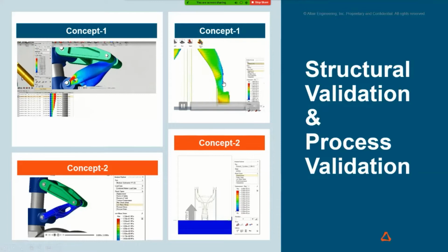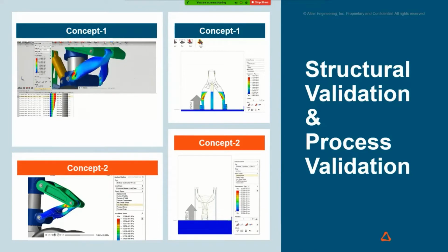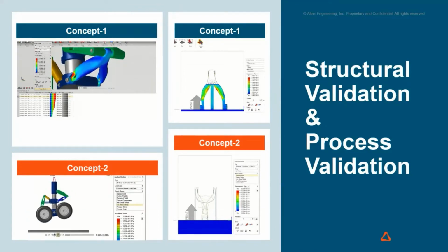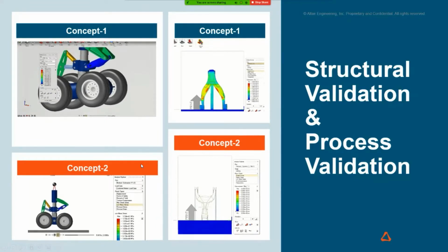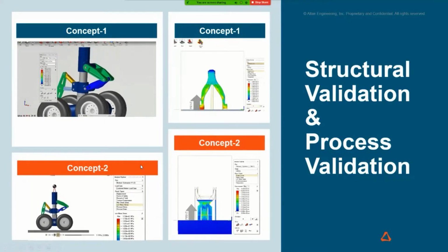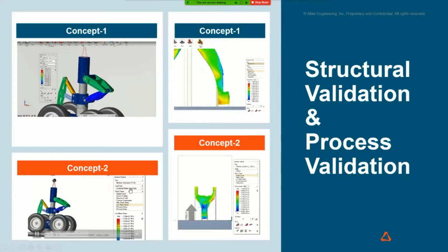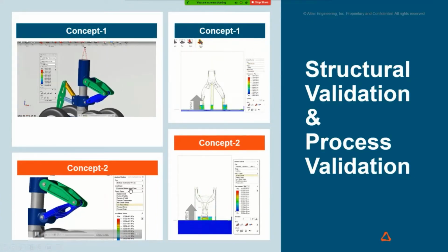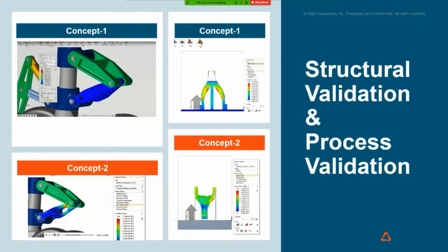The reason we are doing this is because we want to understand the maximum distortion, the residual stress, and the thermal behavior of this component, and we will understand that by doing the simulation of the 3D printing process for both of the concepts. And all this will help us to choose the right concept, and that's the whole purpose of this workflow, where you start with your existing design.